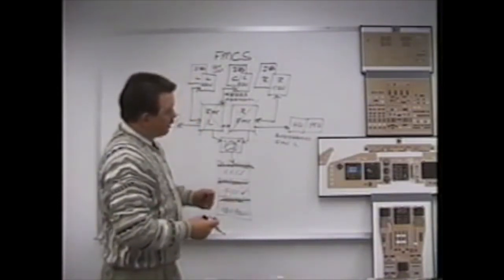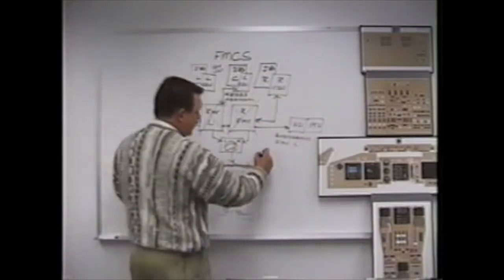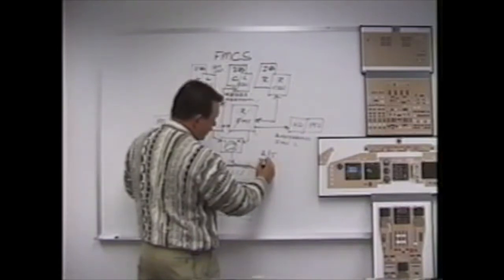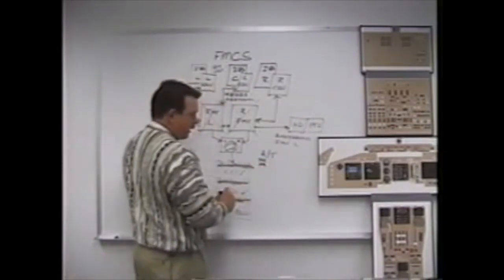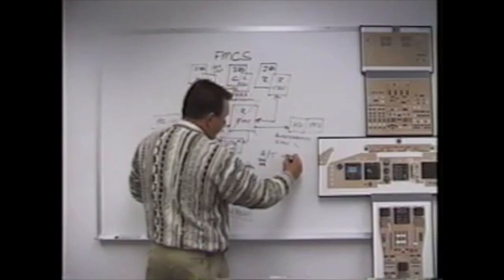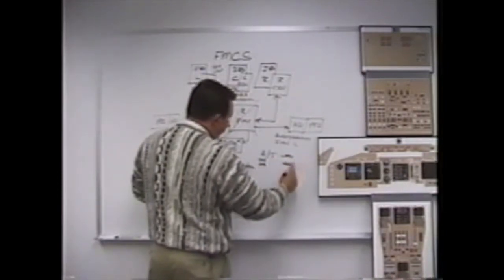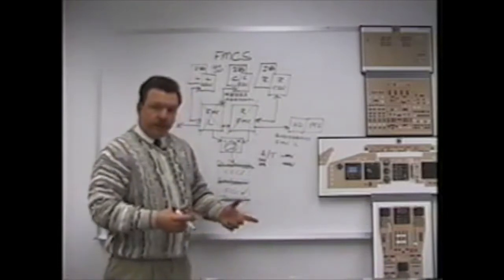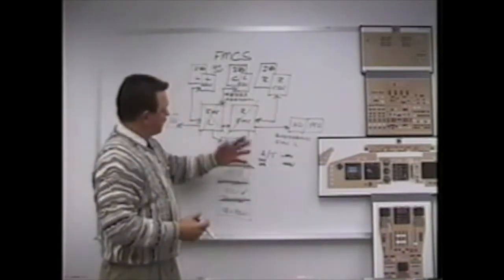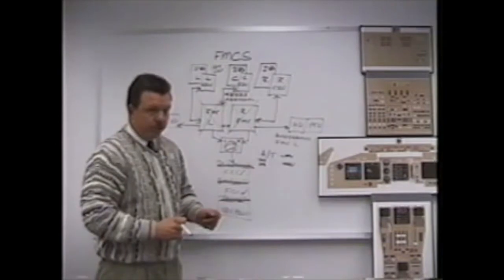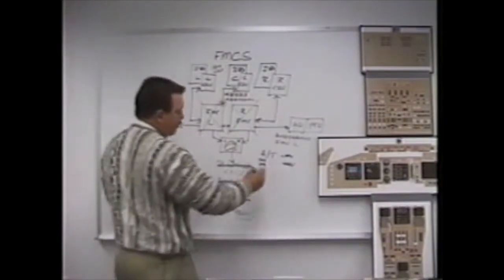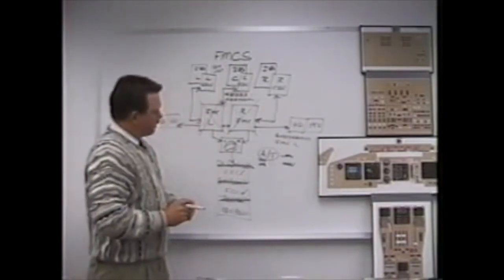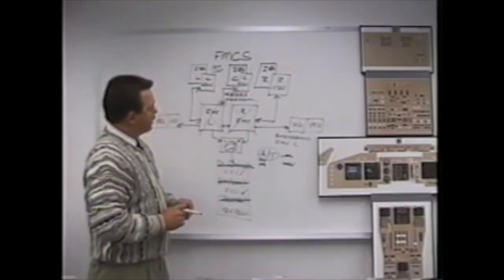Well, if we look at our mode control panel, the things we've lost are auto throttle function, so the thrust and speed mode of the auto throttles are gone. We lost LNAV and VNAV. Everything else works. In fact, you're basically on a 747-100, a classic 747. You have everything you still need to shoot a Category 2 approach. You cannot do the Category 3 approach because you need the auto throttles per limitations. So in standby nav, we can still get a Category 2 approach out of it.